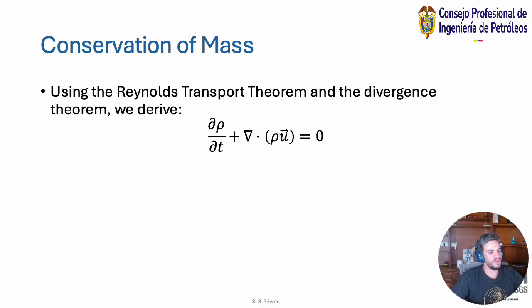And from a physics perspective, this is the starting point for deriving the diffusivity equation and the continuity equation in petroleum engineering, right? And what you can see from this, if you're talking about conservation of mass, is the conservation of the fluid, how it changes from one state to the other. That allows us to really understand how things are behaving from a mathematical perspective and a physics perspective when it comes to fluid analysis, right?